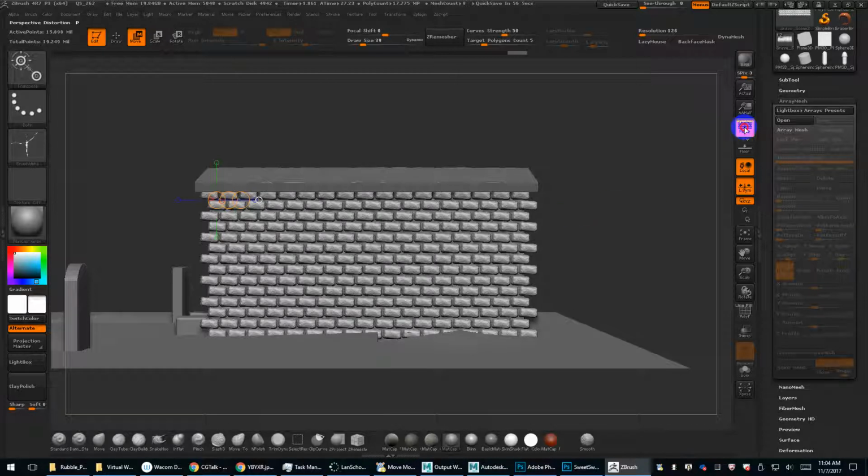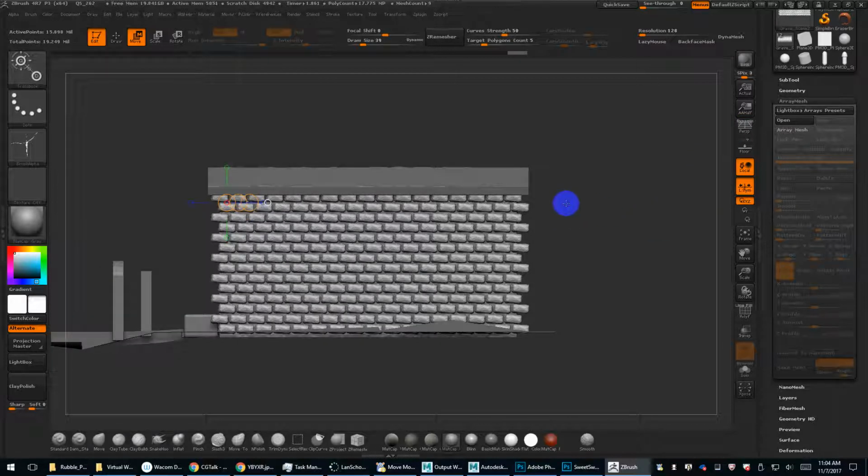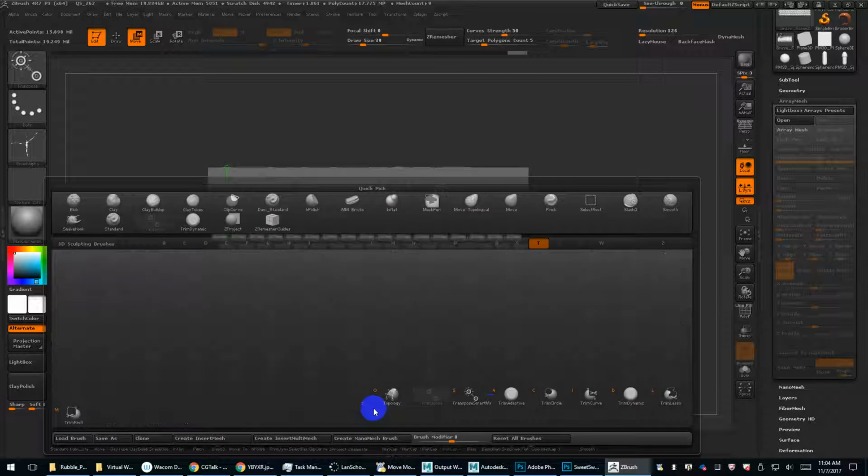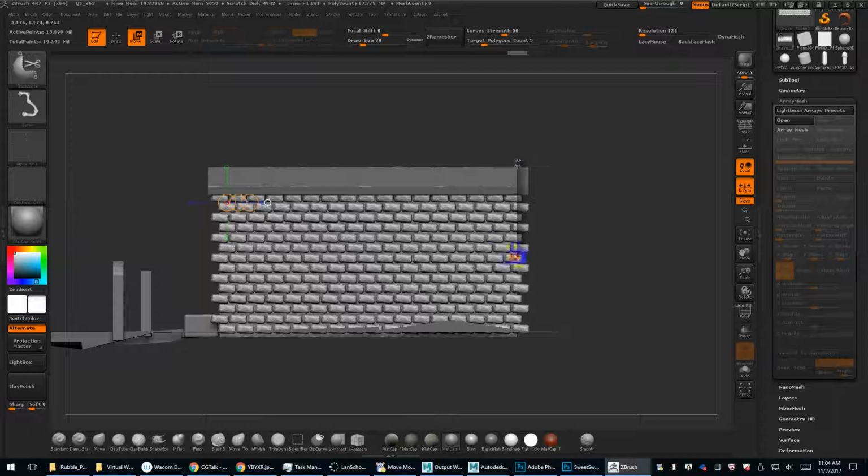So in this case, I'm going to turn off perspective, and again, I've kept my building roughly aligned to a left-right XYZ axis, right? So remember, I can go B for brush, trim, because I want to just slice the ends off and have them capped. So I'm going to go trim, curve, and just come across like so.